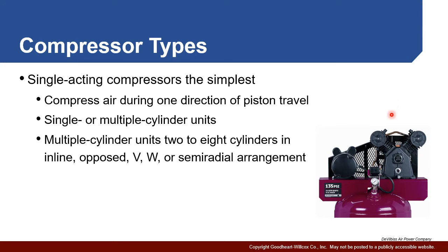In fact, what happens here is the larger unit pressurizes the fluid up to a certain level, then the air travels to the next unit that then pressurizes it further. Right? You can do this with multiple cylinders, anywhere from 2 up to 8 cylinders, and you can have multiple stages, or you can have multiple cylinders doing the same pressure range.